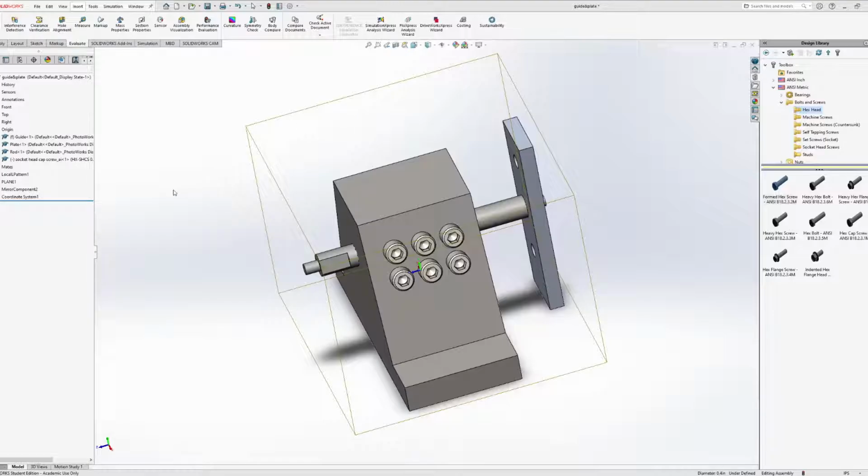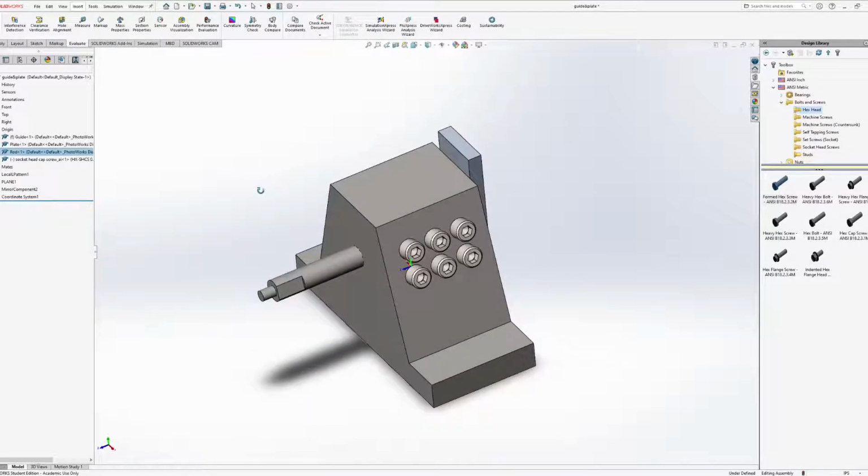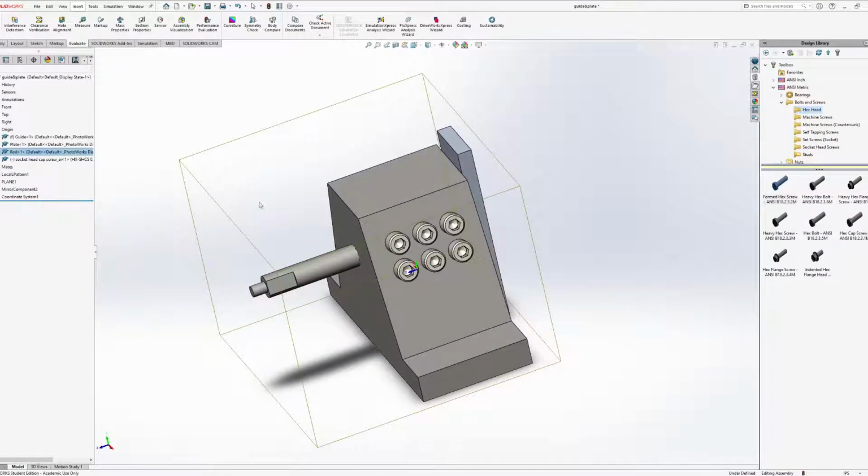Because if you're clicking on different parts within your SolidWorks assembly, or perhaps just a specific part, and then you click on a different part and recalculate, it might throw the center of mass for one part somewhere else as you shift it to a different part. That might have been what happened. So like right now, it's just this guy, but if I move this over, it's only a little bit different, but it's fairly similar. Okay. Was that perhaps maybe the issue?